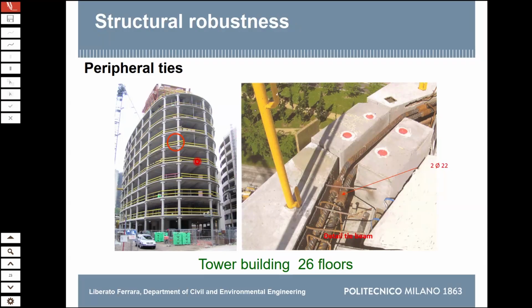So the issue is that you always have additional reinforcement, or you have two separate reinforcements, and one is designed only for the tie action or whatever, and the other one is designed for persistence. So the principle is, however you design it, you have to keep the mechanisms separate. So this was just to give you the flavor of what robustness means. Okay. Well, that's done. How do we do that?